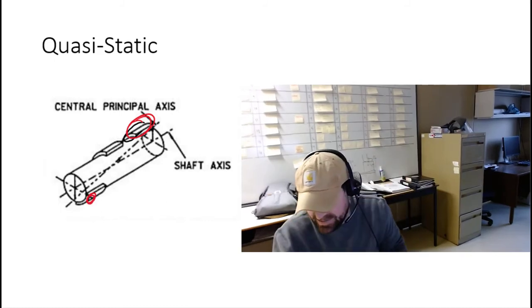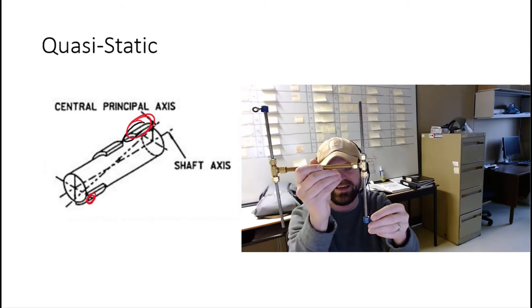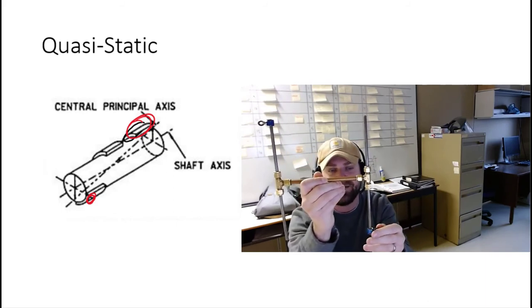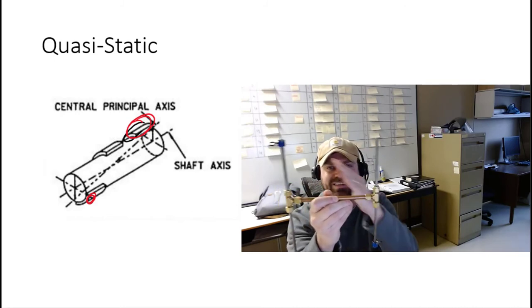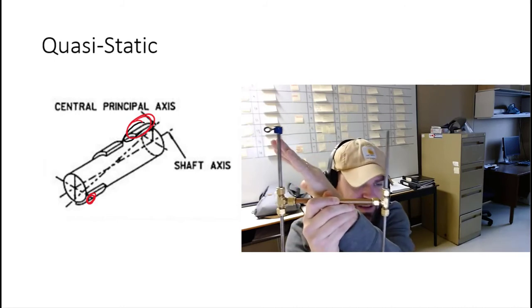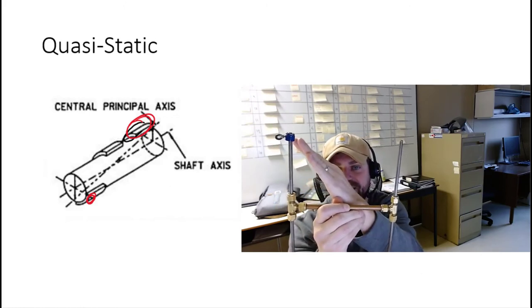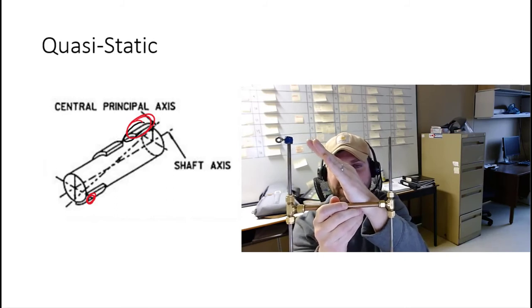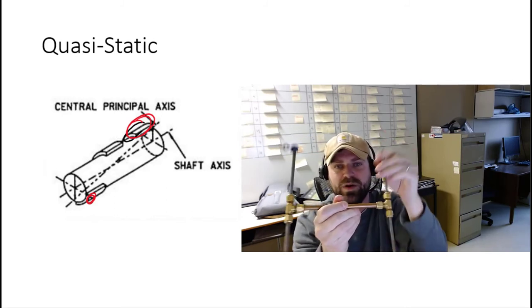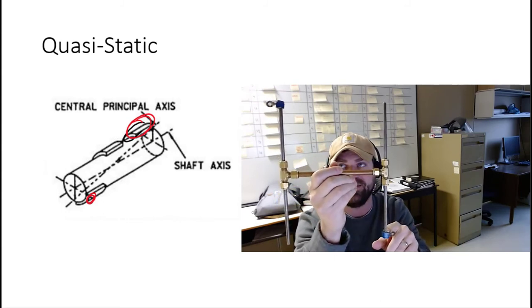So it's like looking at a couple imbalance. If I was to take this couple imbalance setup and add more weight to one side, instead of taking the center line that runs directly through the center, it's bringing it over slightly. So it will find a home, it will find a center where it's always going to land at the bottom.